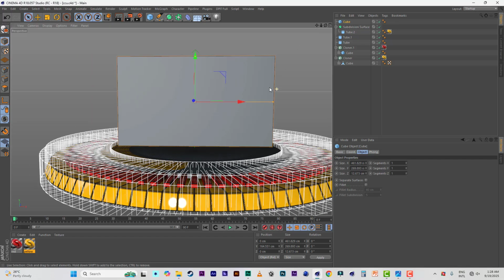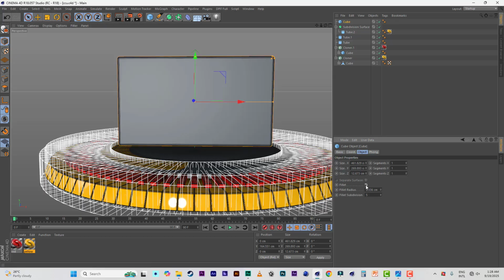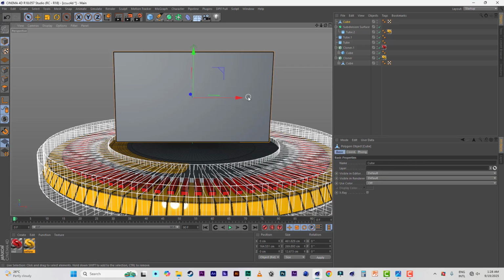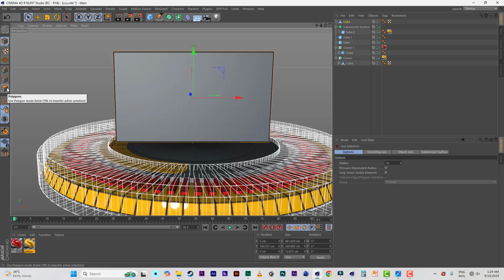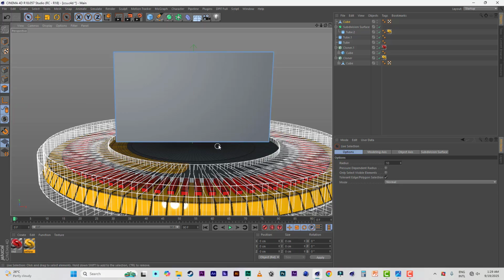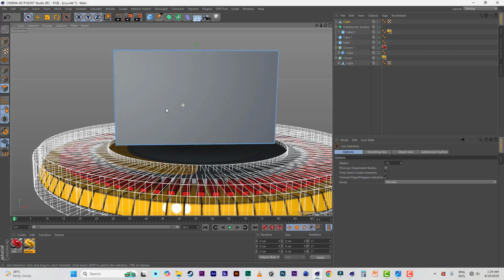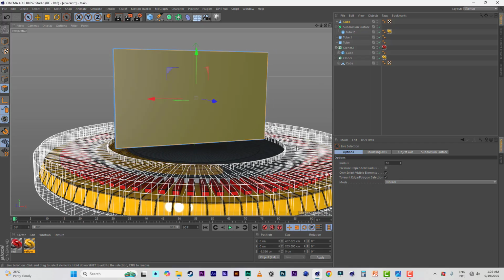Now let's make it editable. But before that, let's select the fillets to smoothen, 2 centimeters will be okay for this. Now you can make it editable. So press C to make it editable. Then let's select the surface polygon here. We need only the face, okay? So let's select only visible elements so that we won't select the back too. So let's select the face.